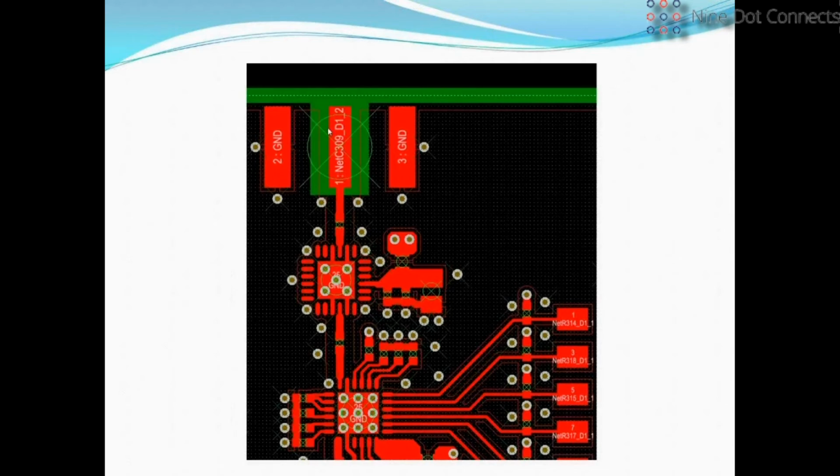What I'm showing here, and the purpose of this slide, is to show you how the green area that you see here is a negative image, and basically this block is going to prevent ground from residing right underneath the surface mount land area for the center conductor of an SMA connector. And the purpose of the ground being forced away from this area is to maintain the 50 ohms that is desirable.